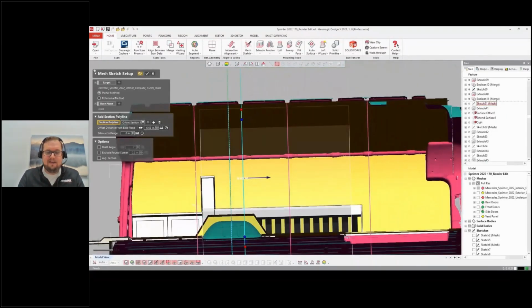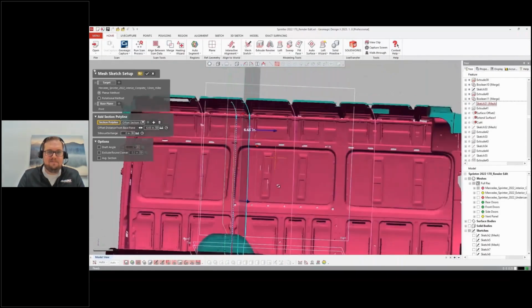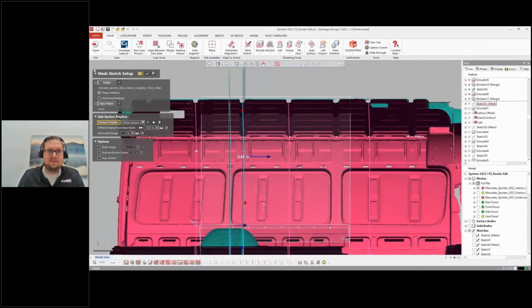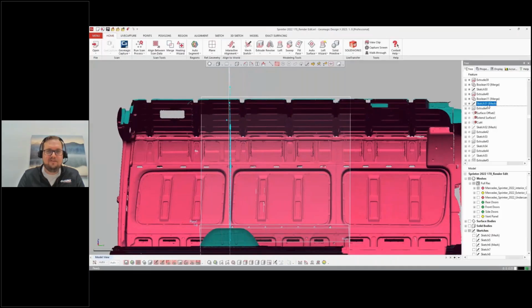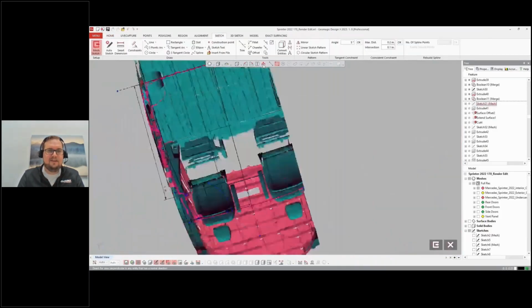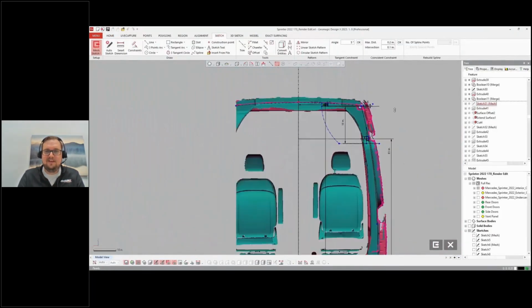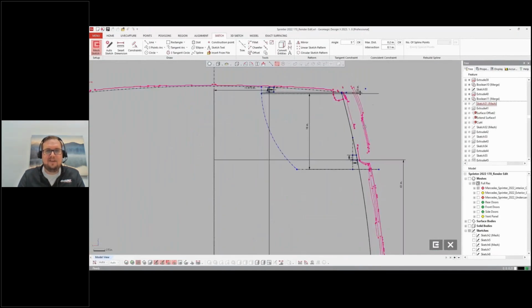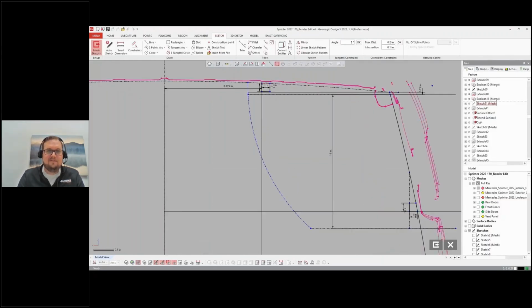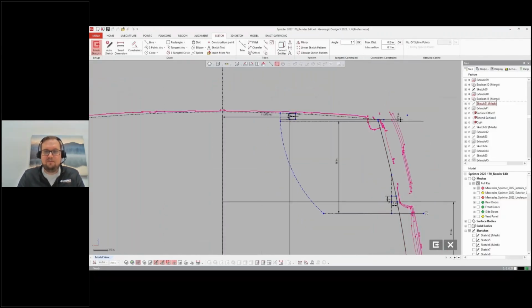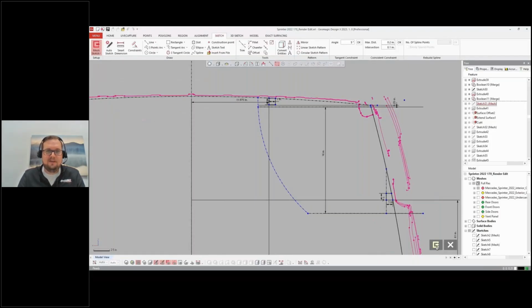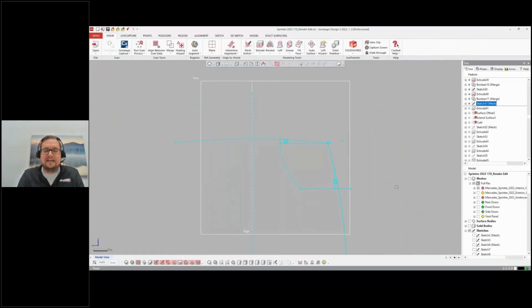So our upper cabinets give us a bit of a challenge because we need a solid surface to mount them to. So you can see I've taken multiple cross sections across the ribs of the vehicle as well as that side support brace. What this allows me to do is mock up my cabinet in a sketch, but really lock in these two square mounting areas here. So these mounts, whether they're a U-channel style rail or just a wooden purlin style mount, we have an exact location for where those need to be, so they're not going to interfere with anything.